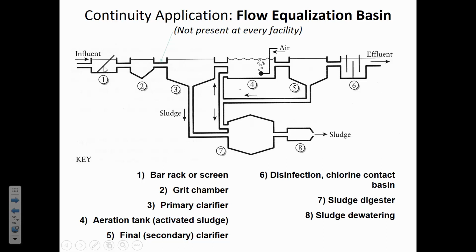And it seems like, well, who really cares about that? But if you don't have dissolved oxygen in the river, then the anaerobic degradation of waste has a horrible smell. It forms hydrogen sulfide, which is a poisonous gas that's toxic. It can kill fish in the river. So it was pretty common to see downstream of major metropolises just huge fish kills having to do with the sewer treatment. So the big innovation that changed that was the process called secondary treatment of sludge.